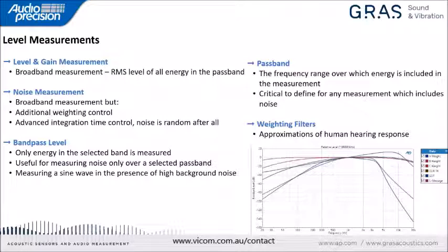If we're measuring noise, a true random signal, well, there are a couple things that come in. The first is there is a literally infinite amount of noise in the universe. That is to say, as you increase the bandwidth of your analyzer, you will keep measuring more energy.